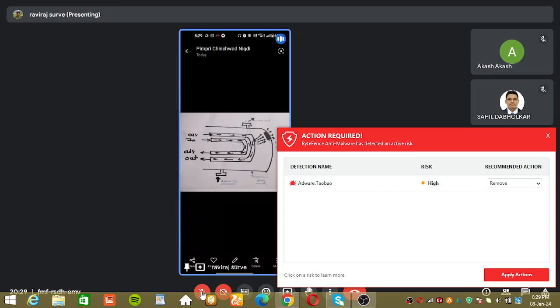Okay, the reason we use the bursting disc is that, as you can see here, air is circulated through the tubes. If by chance the tubes get broken, then this highly pressurized air directly enters this area, where water is circulated over the tubes, and this area will be over-pressurized. It will burst directly, as it is made of cast iron, and it will damage the operator also.